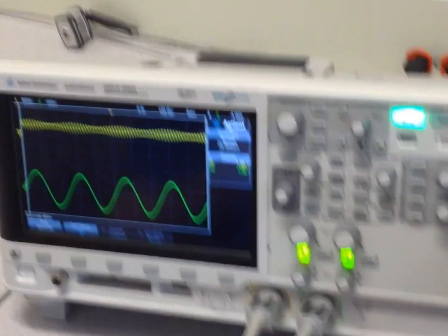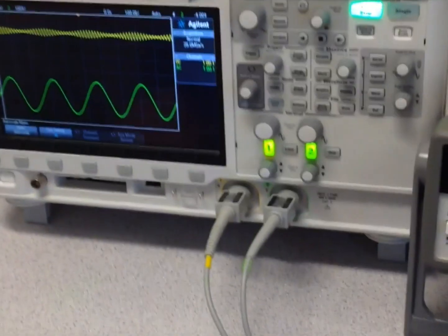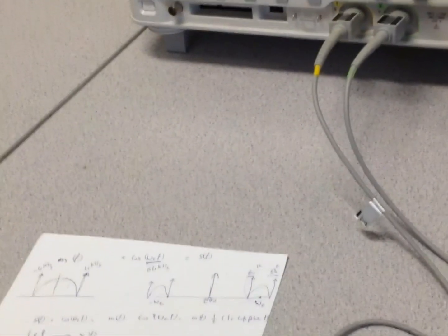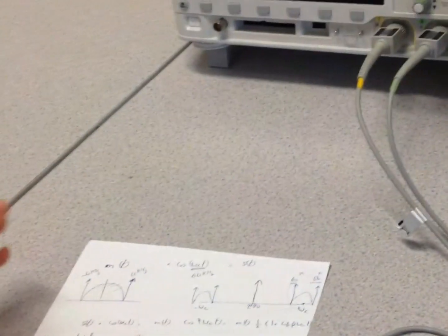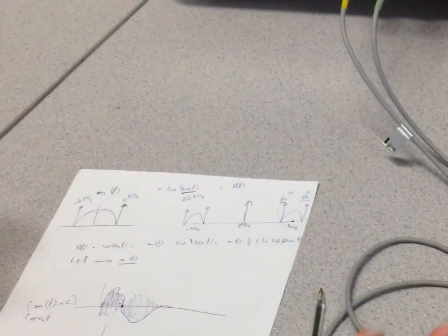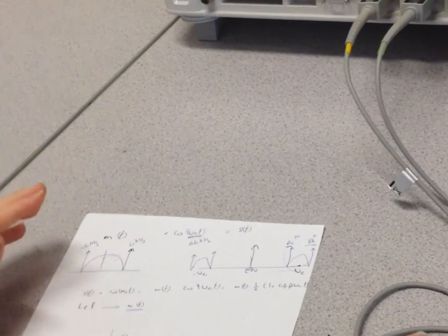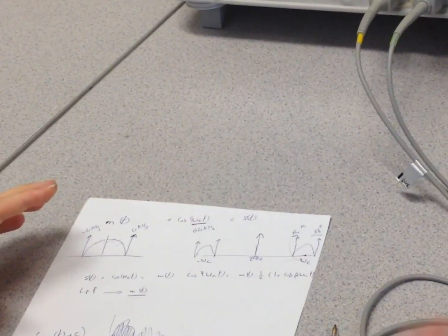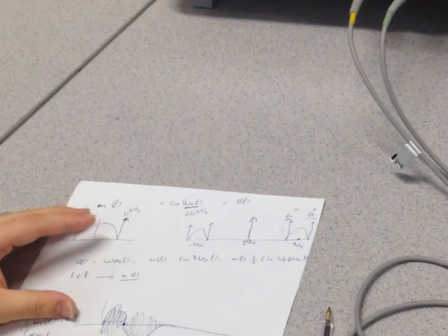Okay, if there is some benefit of adding a constant to my message before multiplying by the carrier, is there a benefit of making my message all positive? Yes, there are easy-to-implement detection circuits. If your message is all positive, there are very easy detection circuits, mainly called envelope detectors, that can detect your message